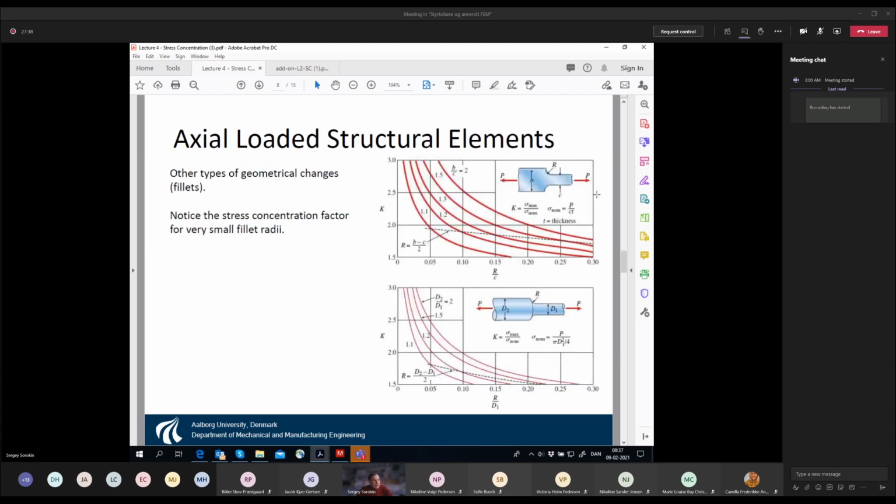Just let me show this kind of curves. So here these are the tables, but I think it's not what we have to do immediately. Just for your information, we have uploaded plenty of similar curves from the book Design of Mechanical Systems by Norton. There these stress concentration factors are presented in this graphical form for different cases of loading and for different concentrators. So it's huge work which was summarized maybe something like 100 years ago and then verified with experiments.